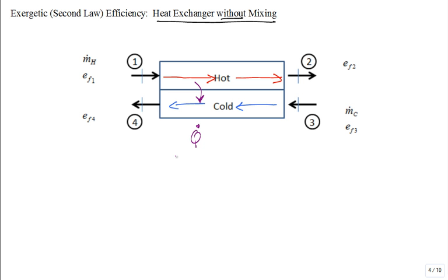Now, whenever you have a heat transfer, do you have exergy transfer with that heat? Yes, you do. A lot of times we'll draw it like this, E dot Q. So there's an exergy transfer from one fluid stream to another fluid stream in this heat exchanger. Okay, let's define an exergetic efficiency for this. It's really a counterflow heat exchanger. Sometimes I'll add a subscript on that to help clarify.